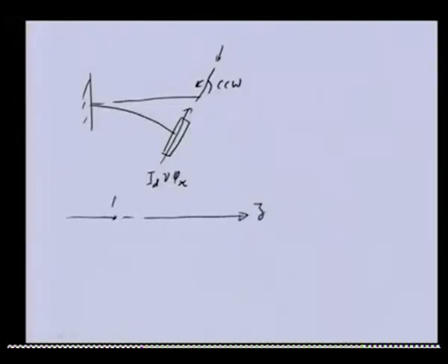Let us say point A, which was the cone apex, is this one, and let us say this is the disk center line, and we had an angular momentum in this direction, and there is another angular momentum, this one, which has magnitude ID nu phi x, and this angular momentum had magnitude Ip omega.